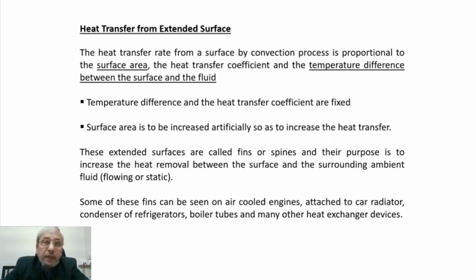So there is an effort to increase the surface area so that the heat transfer is enhanced because of enhanced area. As we have already said, the heat transfer coefficient and the temperature difference for a given situation are fixed.